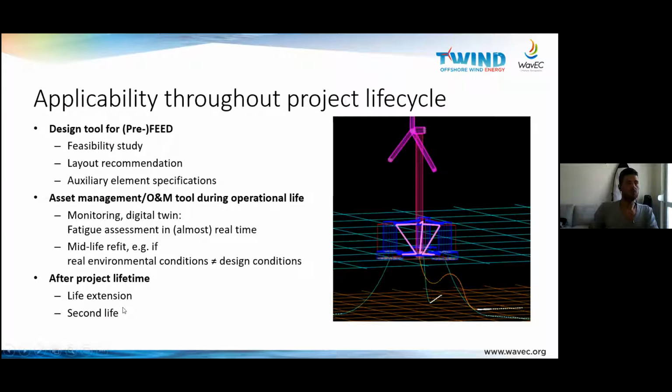And if you know the conditions that the cable was experiencing during those 5 years of project lifetime, you could use a tool like ours to estimate what fatigue damage it has experienced, and what remaining lifetime you could guarantee for that cable. So this is also interesting for reselling or for reusing the cable.